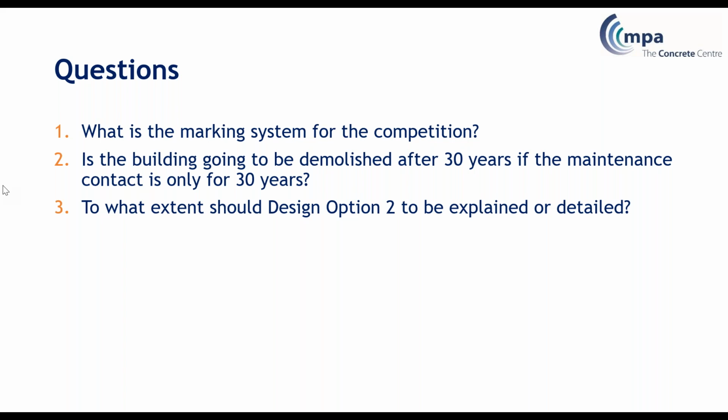I have assumed that this building will be one of several on a road, and they will all have this, so it will be next door to another building which will equally have an entrance in at ground floor and an entrance at the lower ground floor at the back, and you don't need to worry about taking a retaining wall round the sides of the building. So it's just one wall that you need to worry about with the retaining wall.